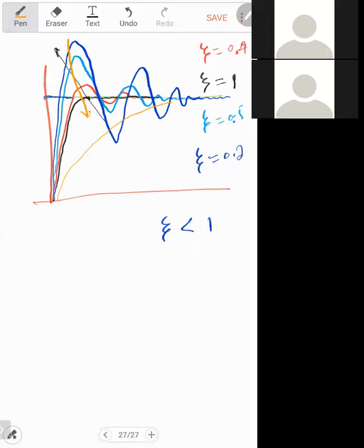So this means that it requires proper design to find the response, the system poles, which give you a very smooth rise, like the critical case over here. So a smooth rise, and you see it steadily comes into the final steady state position. So smoothly come into the final steady state position.